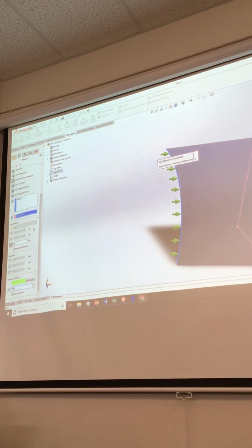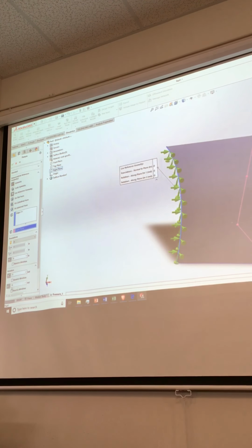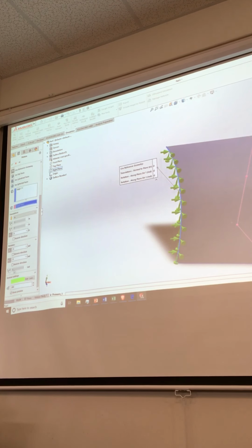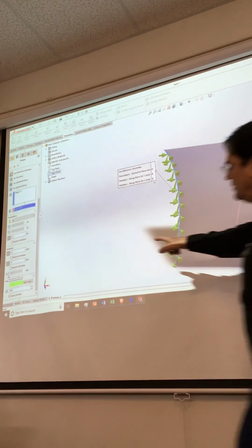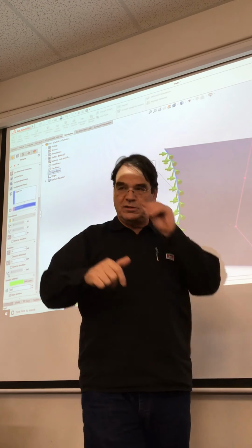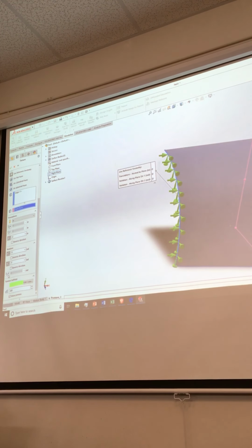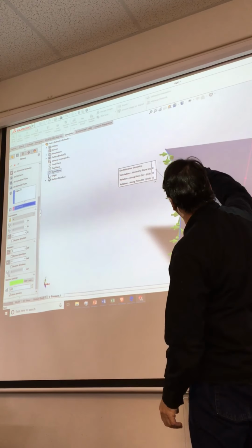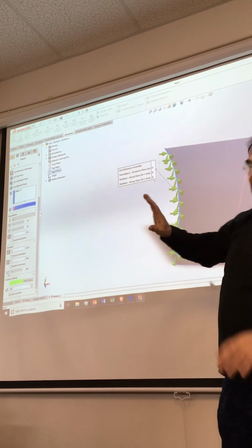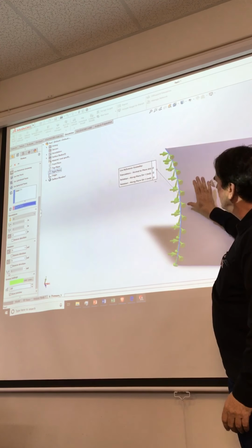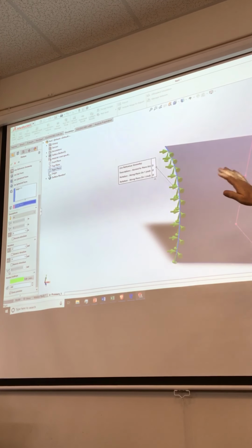And so I need to fix those rotations, and those are these two here. This one here and this one here. Okay? This one here is the in-plane rotation. Right? Remember, when we define a rotation, we're defining the axis about which it rotates. That's what we're defining. And what this allows it to do is it allows it to move in the plane. It can move in the plane, in and out. The tank can get bigger. And it can actually rotate this way in the plane as long as this cross-section remains in the plane. What it can't do is rotate out of the plane.